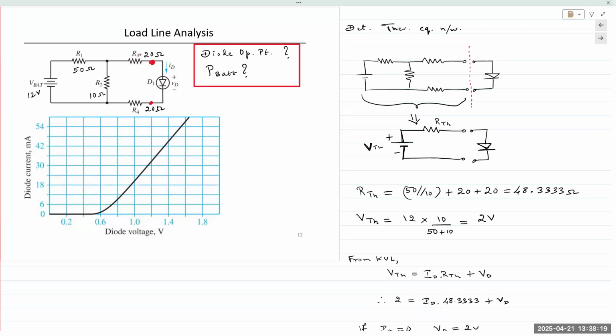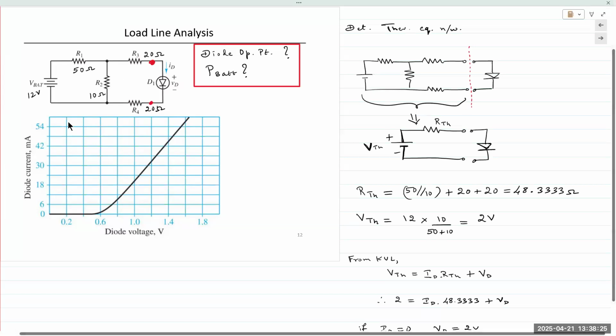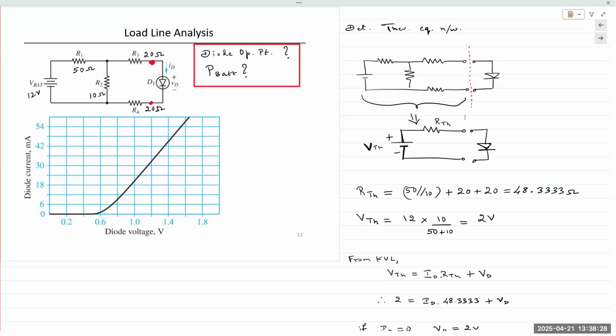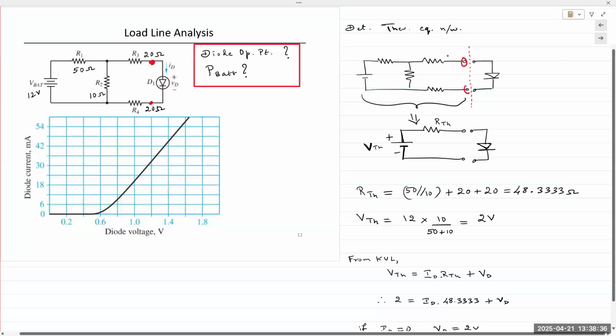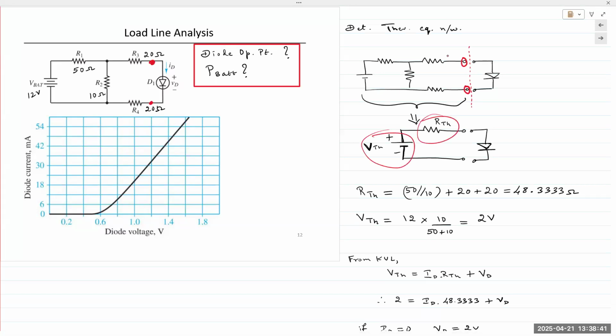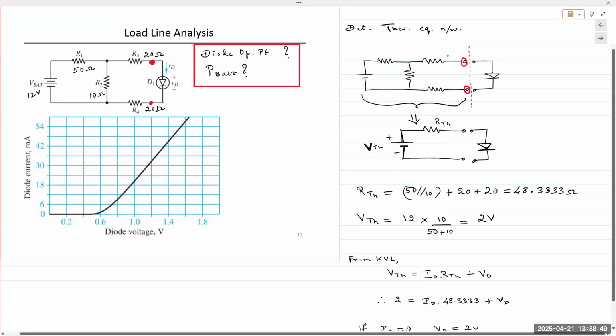In general, to determine the Thevenin or Norton equivalent circuits, you always remove that component from your analysis. When you remove components from your analysis, that leaves behind 2 open terminals. Then we analyze the circuit between those open terminals to give us one single voltage source and one single resistance. That would give us the value of the voltage being applied here. And so that's what you're going to do.